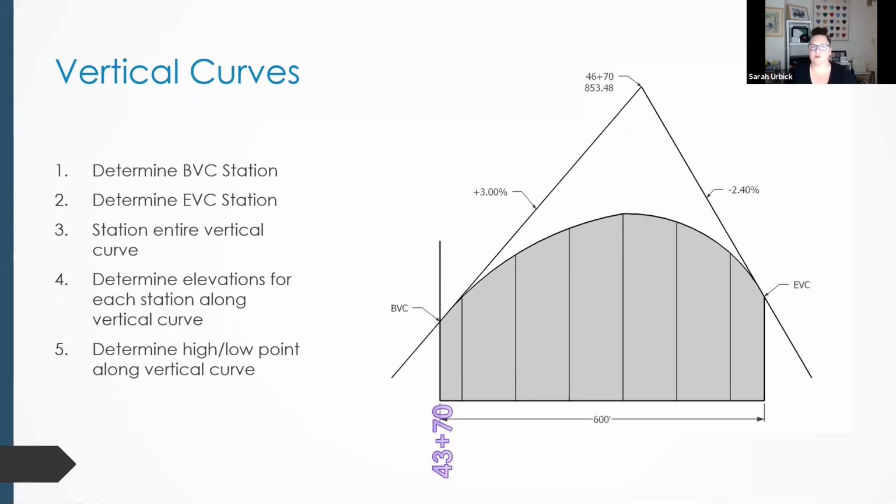We are looking at our point of vertical intersection. The intersection of our tangents is going to be the midpoint of our distance. So I think, Olga, what might be throwing you on this one is that it's not the high point. The vertex of that intersection is not always going to line up with the peak or the lowest point. Okay, we'll get to that too, because we have to determine the high and the low point here, which I realized I forgot to do on the slides.